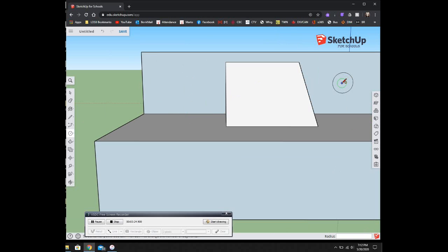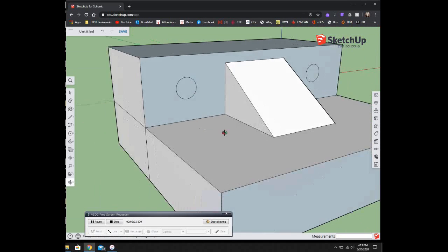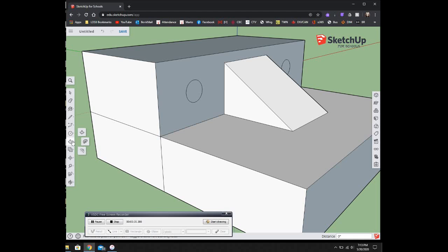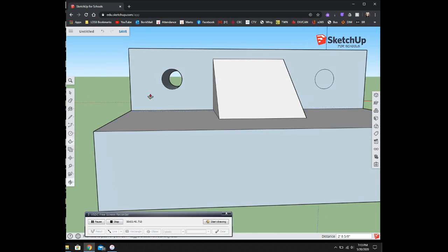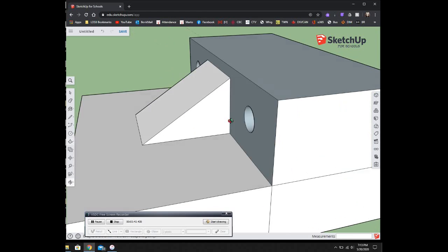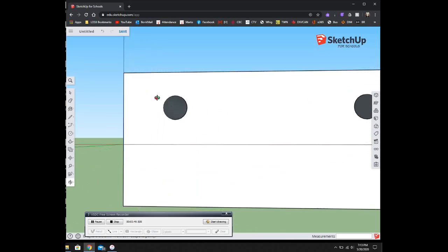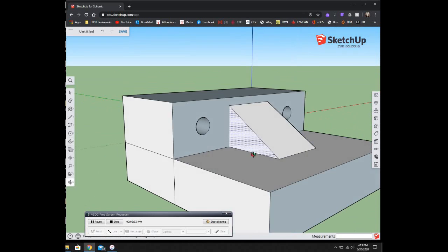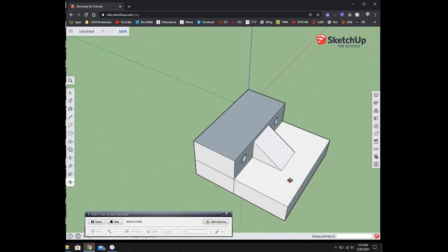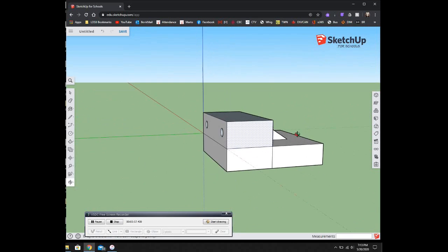Now this is creating a hole feature. And you can see I'm just lining up that previous circle with the midpoint to get things lined up. And now I'm going to create a hole feature. So I'm going to take push-pull and I'm going to push it into the object. If I push it in and then click the back edge, it creates a hole. But I can extend it further. So you can see I click the back edge for the second click, and there you go.